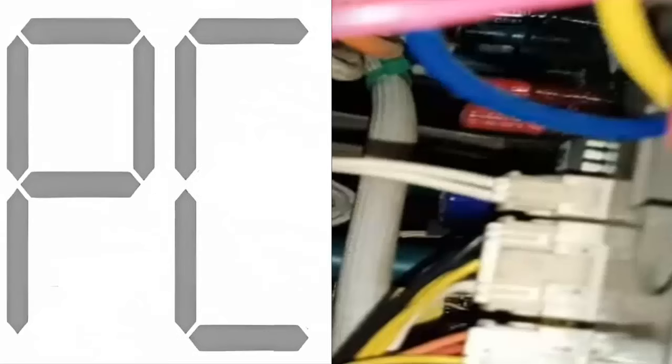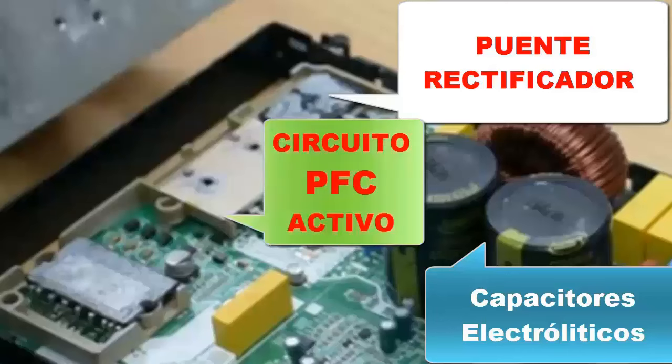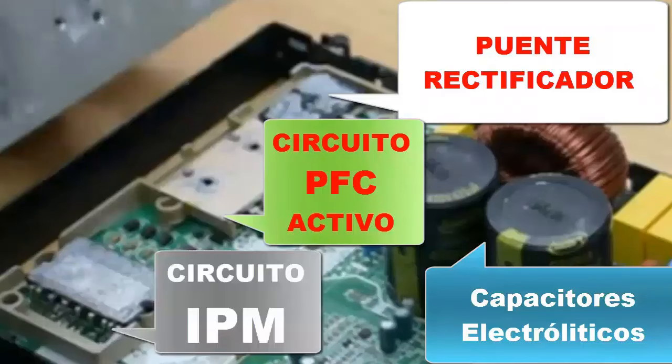D. The third step focuses on the PFC circuit and the IPM electronic module, which are crucial for efficiently converting the AC supply into DC, and any significant deviation in voltage can cause operational problems. Therefore, we will connect the electronic board and measure the supply to the IPM electronic module.